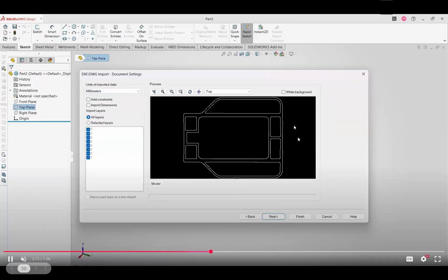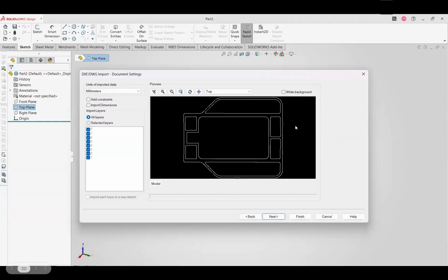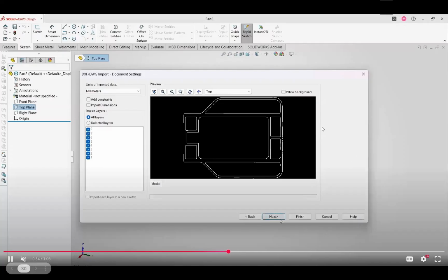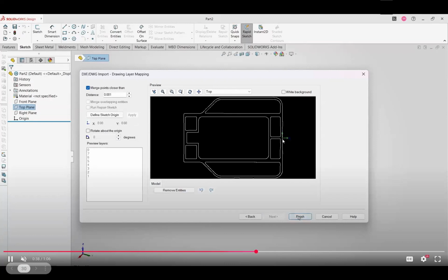And here you see the preview of the contour that you are about to export. You can modify it here, but honestly, it is easier to get the necessary positioning of the contour in Artec Studio. So I almost never change this positioning in this window.